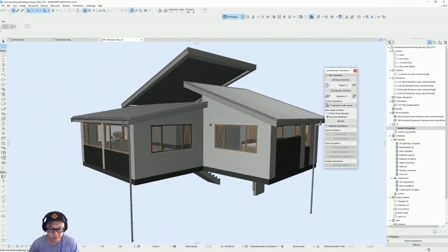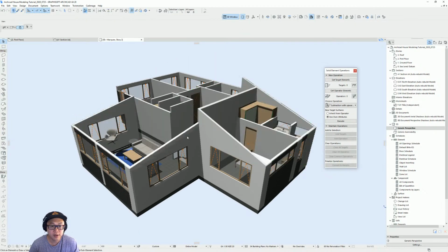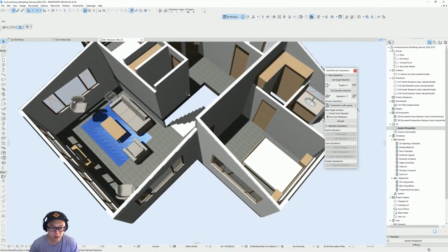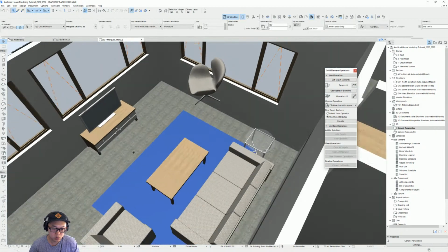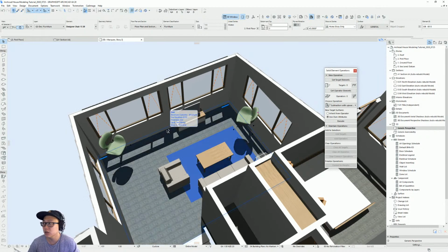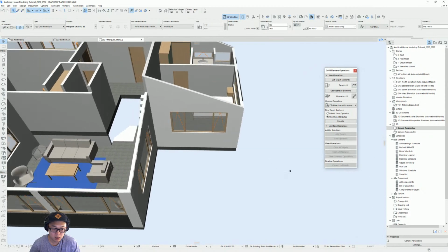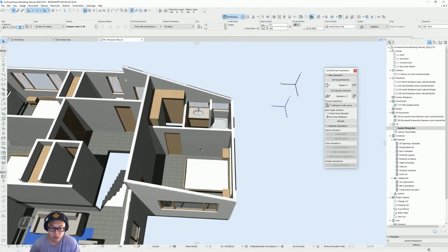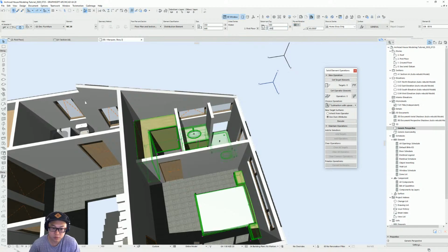And yeah, I didn't want the roof, so what I can do is just click on those and try to hide them so I can see the inside. And this chair is floating, so I'm just going to select this one and this one. I'm pushing shift to add some elements to my selection, and I'm going to type -900 bottom, and those as well, -900.